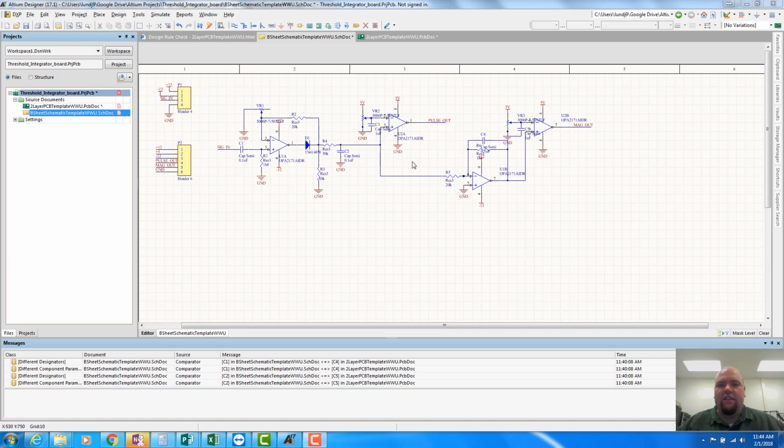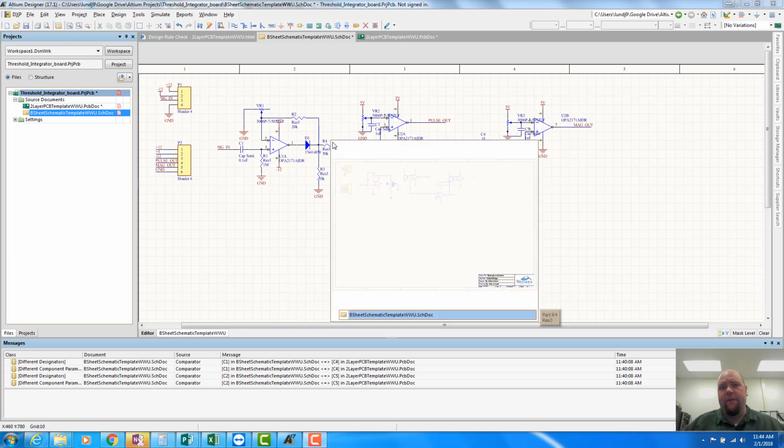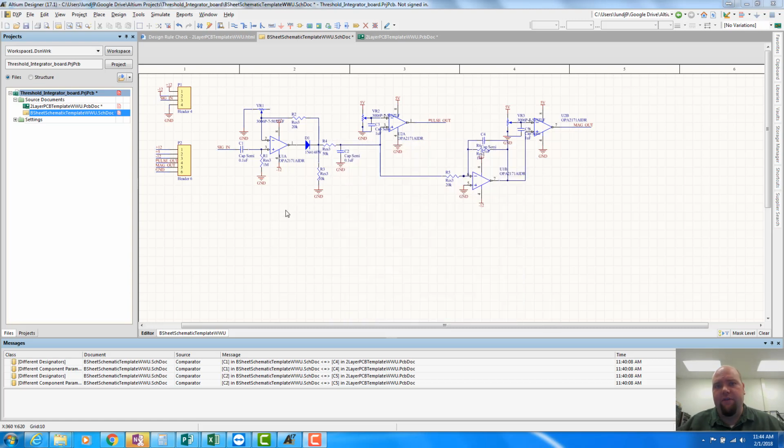And then this op-amp here will take that, and there is an adjustable threshold. The magnitude of that signal corresponds to the magnitude of the AC oscillation here. If the magnitude of that signal is greater than a certain threshold, which is set using this potentiometer voltage divider, then it will rail this op-amp to 5.